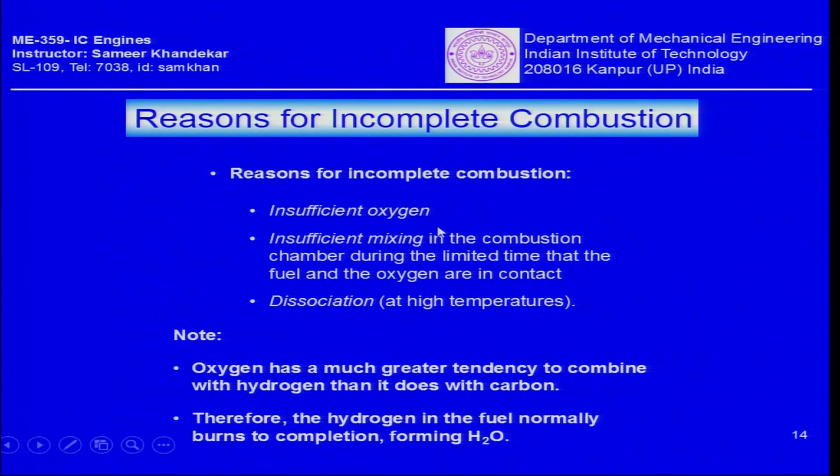Many times you have seen a truck, for example, which is heavily laden with cargo, giving a lot of soot, a lot of black smoke comes out. That black smoke is coming out because the diesel is not completely burned and some of the carbon particles are still remaining, since there was probably insufficient oxygen. That is one reason. Another is insufficient mixing. That means the liquid droplet, the diesel fuel, did come into the combustion chamber, however it did not mix.